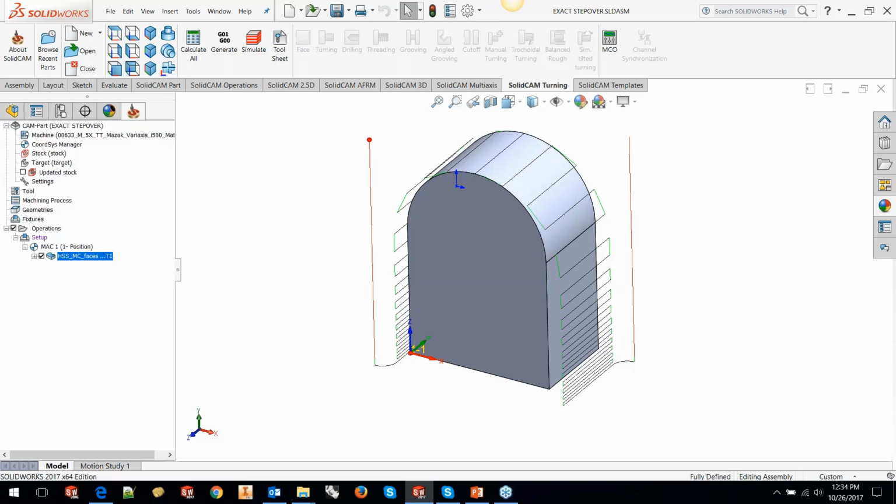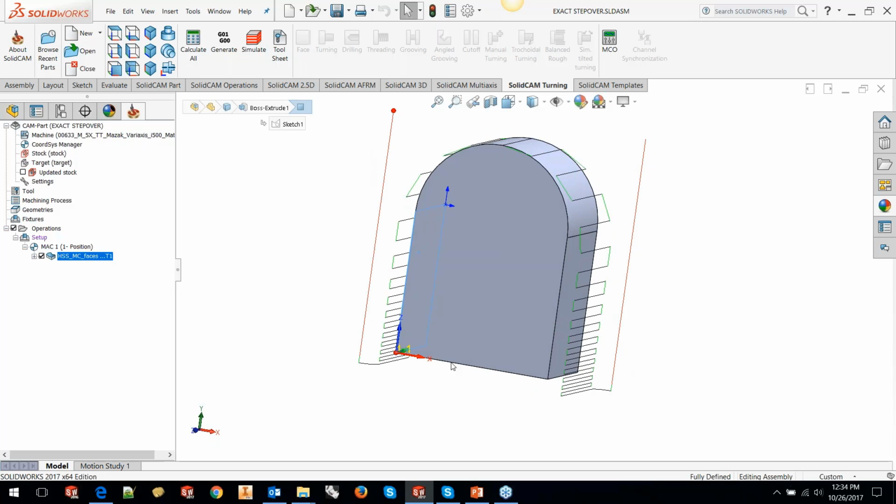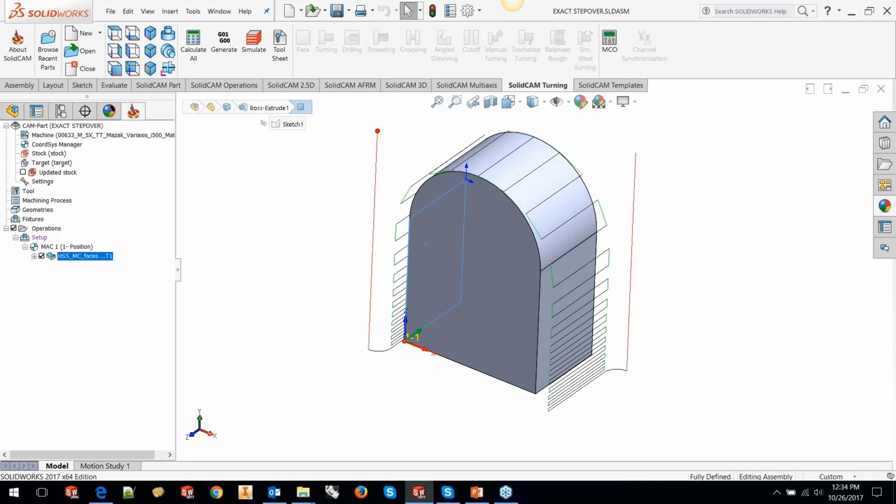It starts projecting on these surfaces, the drive surfaces, basically 1, 2, and 3. It then realizes that the width of the surface is much smaller than the combined width of all these 3 surfaces, so it tries to distribute the same number of passes on these 3 surfaces. What happens, the end result? The end result is that you get non-uniform step over. Sometimes it's really very large. If you're given a depth of cut of 1 millimeter, it can sometimes end up at 5, 6 millimeters in some areas, depending on the steepness of the area and also the width of the surface.